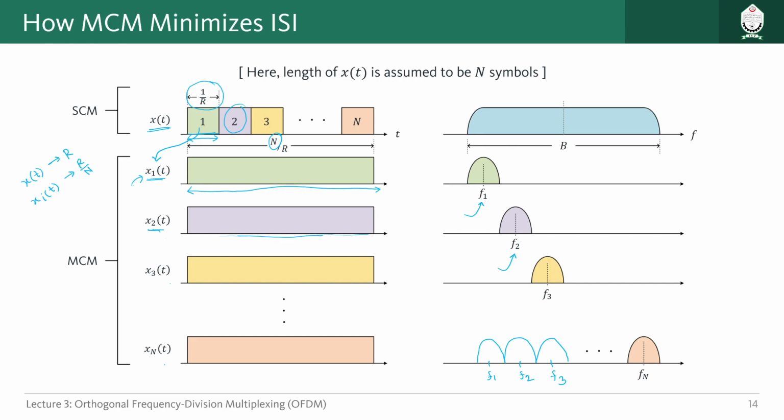We are basically minimizing the effect of intersymbol interference, because we said when our delay spread TD is much higher than our symbol duration, then intersymbol interference happens. Here the symbol durations were very small, right? That's why, compared to the delay spread, they were small, and intersymbol interference was happening. Now as our symbol duration increased, it becomes very high compared to our delay spread.